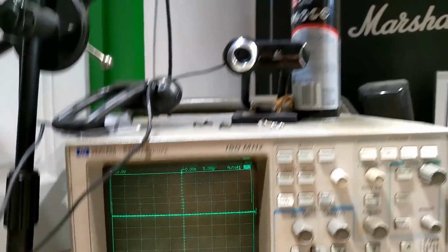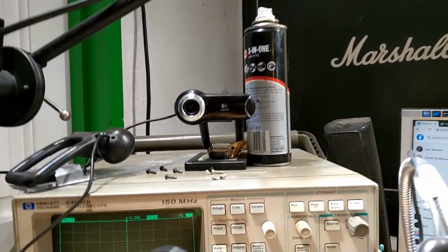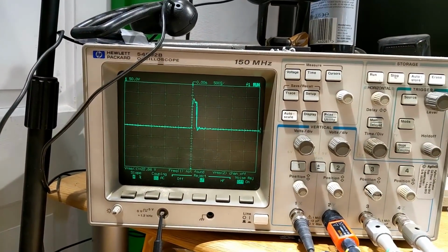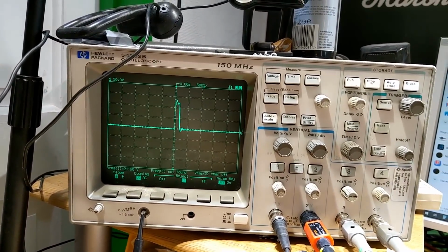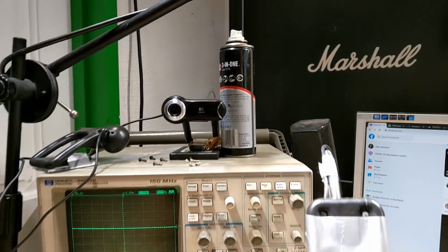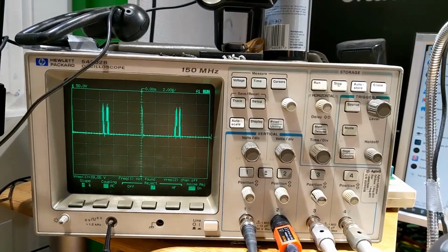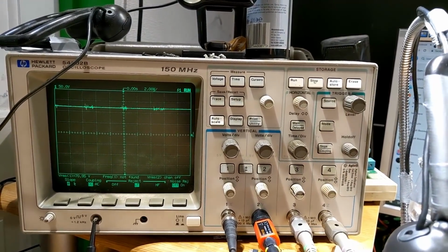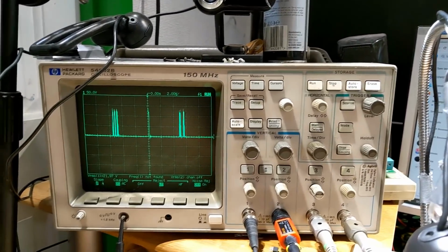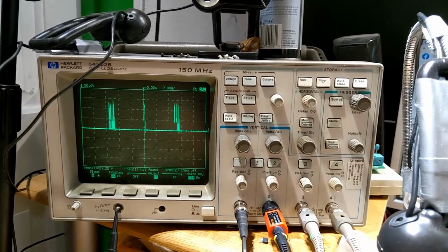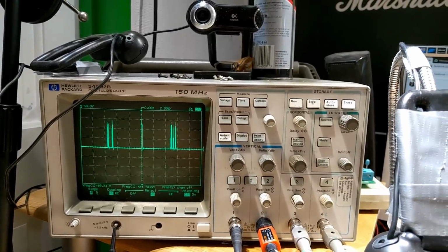I was like, that's not looking so great. Let's zoom out a little bit. Zoom in on the time divide just to show you that again. So we've got just a tiny little pulse, and I was like, hey, that's not right. Okay, what's going on here? This is not something I'm used to seeing. So this is what we have on the low side drain. High side, obviously we've got rail. Low side drain, we have these tiny little pulses like this, and I was like, oh hell, something's not right, is it? So I was like, okay, what happens if I apply an audio signal?